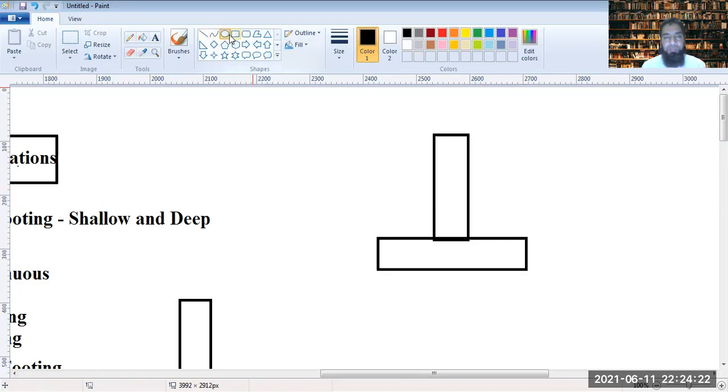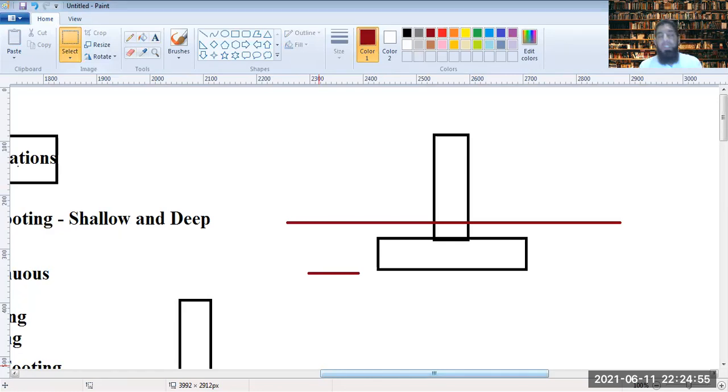Now, there will be, where are we? There is a natural ground, for example, here. This is the natural ground level. So we're actually determining the soil pressure at this point. So this is already within the soil. So while you are determining the gross pressure, it has to include the pressure of the overburden. That's the pressure of the foundation depth up till this point.